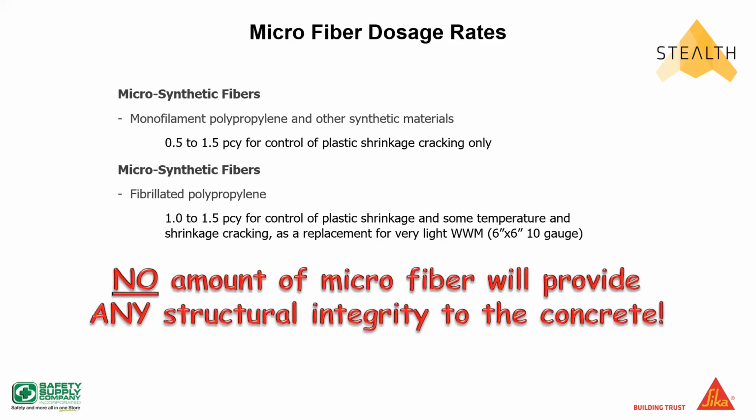Now, this is very important here. No amount of microfiber will provide any structural integrity to the concrete. You can put as much microfiber in your concrete as you want to, but as far as structural integrity, and when I say structural integrity, I'm talking about bending moment, it provides none. Microfiber is not going to help you when you need structural integrity. You need a macro, and we're going to get into that. So I just wanted to throw that note out there to you.